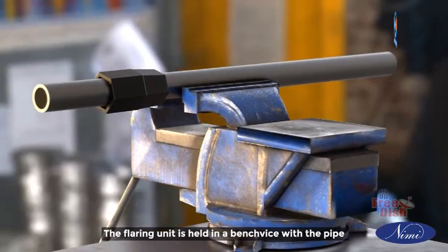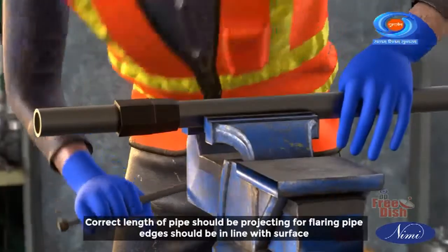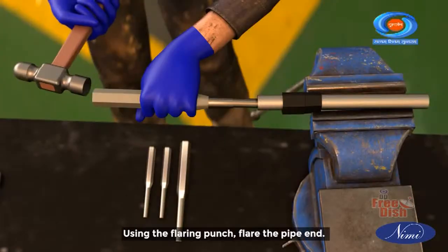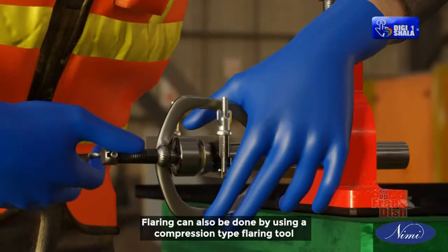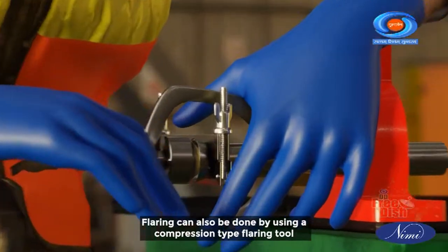The flaring unit is held in a bench vise with the pipe. The correct length of pipe should be projecting for flaring; pipe edges should be in line with the surface. Using the flaring punch, flare the pipe end. Flaring can also be done by using a compression-type flaring tool.